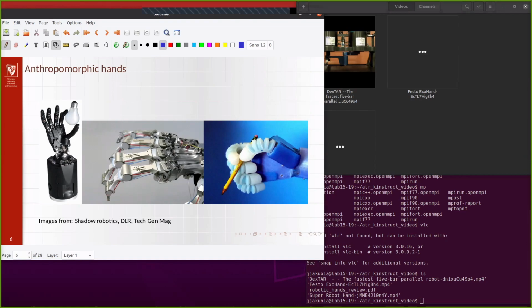In fact, here you have only one actuator per finger, and you are able to deal with quite a high amount of movement. So the two directions: a complicated, complex, and expensive solution from Shadow or DLR, and a quite simple one, as you can see mostly 3D printed, a solution that is cheap, but because of the low price also has some disadvantages.